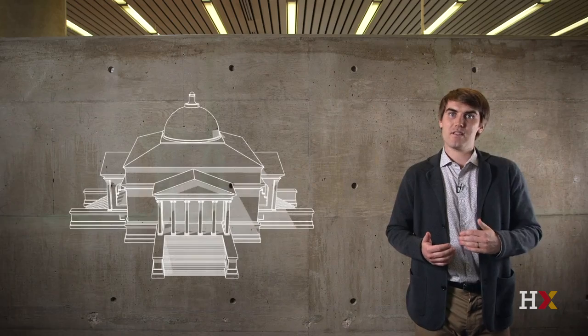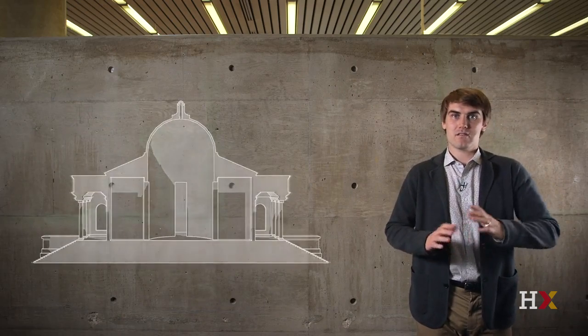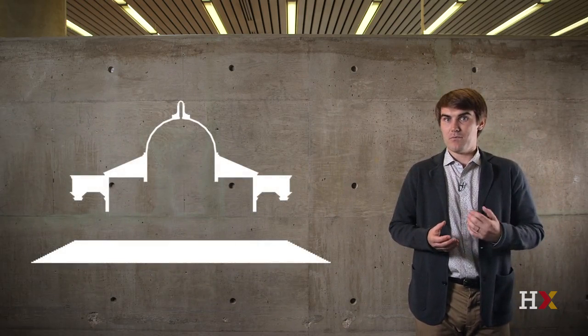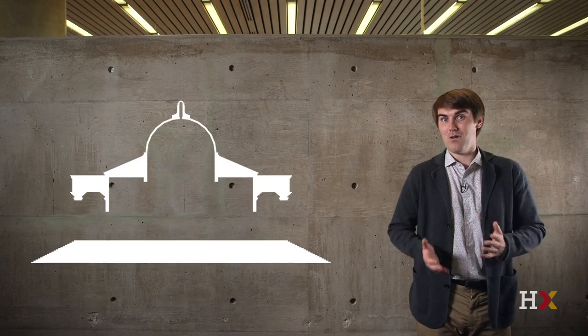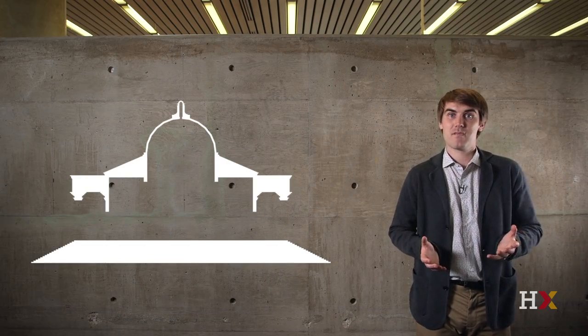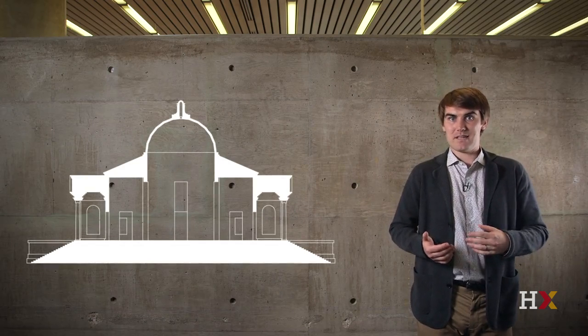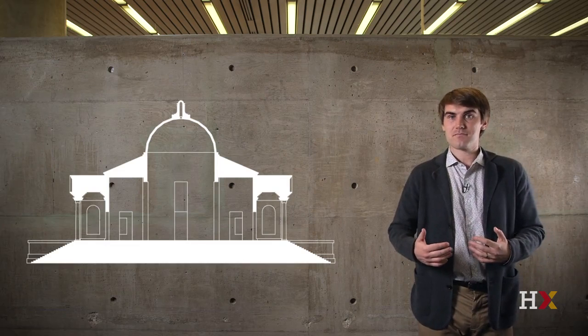The second of the orthographic projections is the section. This is very similar to the plan, except this time we're cutting vertically through the building. Once again, the solid wall that's been cut through has been darkened. And it's important to note that when you make a section, you should never cut through a column because that'll make it look like a wall and you won't be able to tell the difference. Once again, windows and doorways have been drawn with a single line, so we can see that it's actually possible to move between spaces through there.